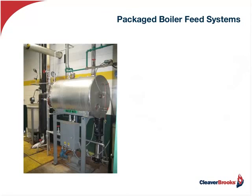So we can return the condensate now back to a condensate receiver, as you see here. But the highest temperature I can hold in this tank is 212 degrees. And it's just going to start flashing at that point. So let's say 200 degrees. That's the best that I can do. So I'm losing that sensible energy. I'm losing that latent energy as well.